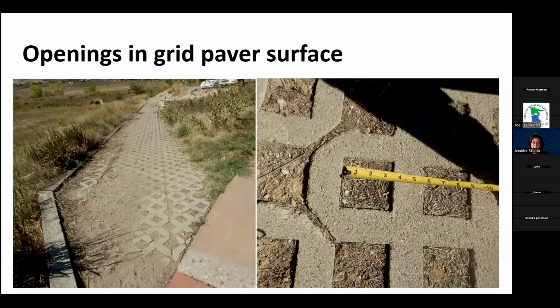We see these grid pavers used a lot in outdoors as well. Maybe the entirety of the parking lot is gravel and the landowner has decided to use the grid pavers for the accessible parking space and the access aisle adjacent to it, which is perfectly fine.